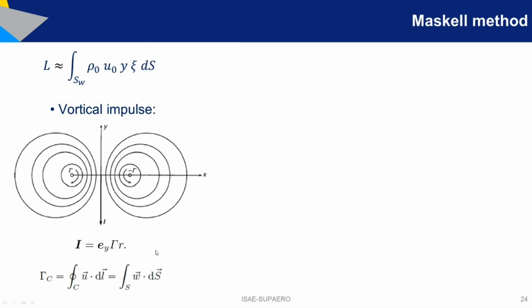And we can even go far beyond. This is the expression that relates the circulation with the vorticity. You know that circulation is the dot product of velocity along a closed curve, or the flux of vorticity. So you need the vorticity and the surface, that's this product here, that gives you the circulation, that's this term here, and then you have gamma, that's the term here.